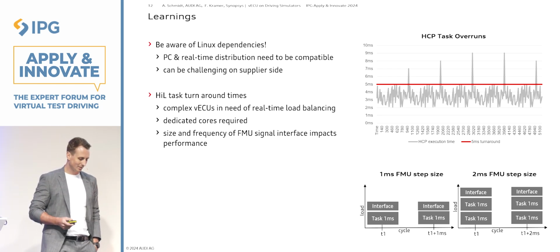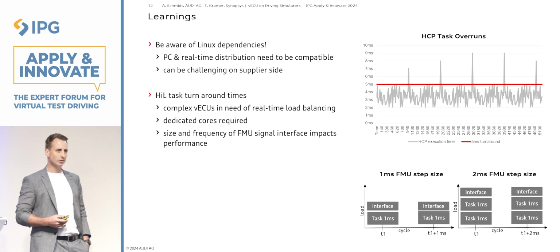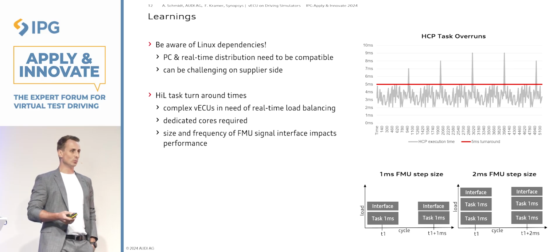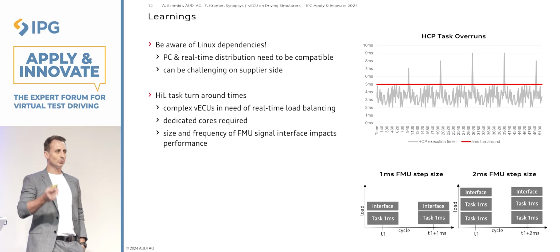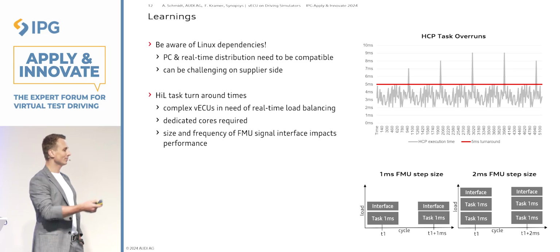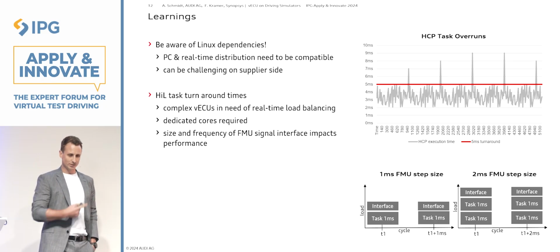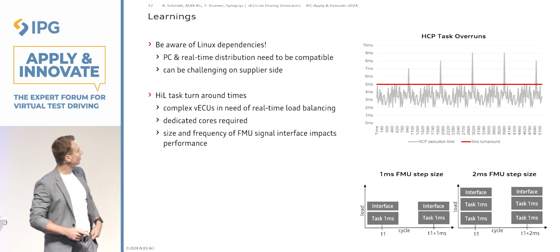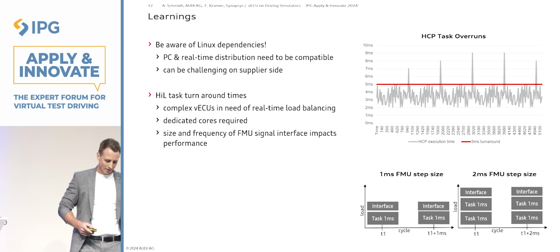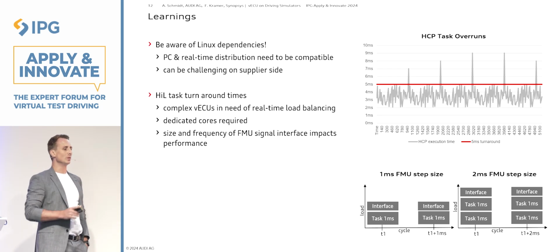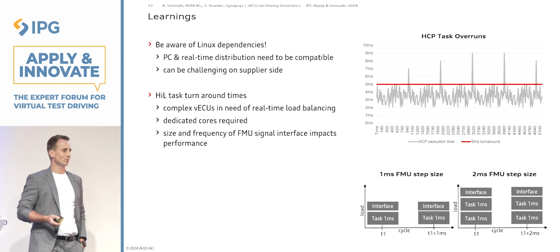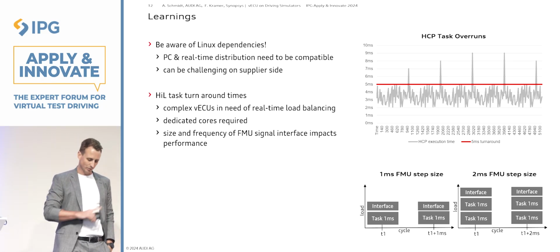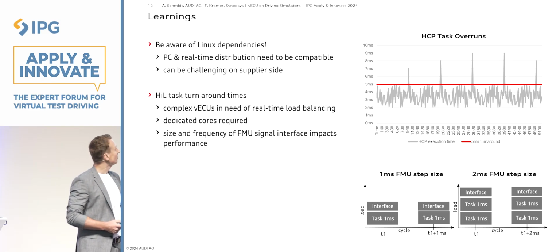That was not that simple to manage, because in a simulation you can be faster than real time most of the time, and it's not a problem. If your setup is running, say, twice real time, everyone says, okay, this runs above real time. A human says that, but a real-time machine can have a different opinion. Let's look at the graph. That was the first execution assessment time-wise. Every second we didn't meet real-time requirements. In office simulations, you don't care about that, because you don't even notice a slight variation in simulation speed. But on the real-time system, they really disagree with you on that.